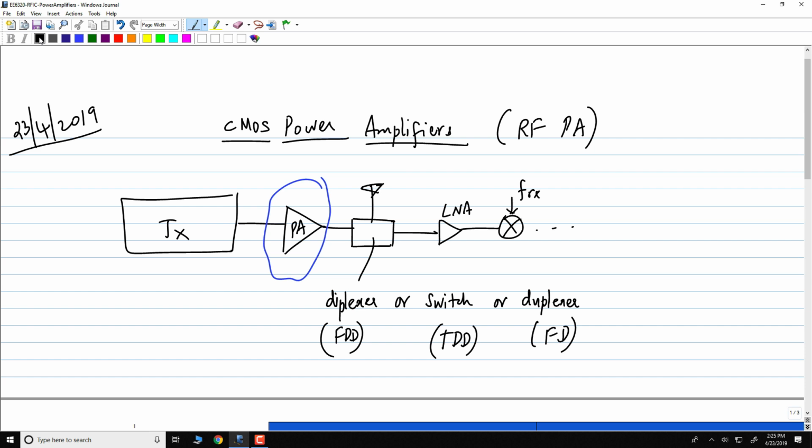We have that SNR floor and other minimum power. The first thing is the antenna itself has a noise floor of minus 174 dBm per hertz, right? Above that you add the SNR required. Above that you add 10 log of the bandwidth of the signal, correct? And finally you add the noise figure that the receiver is going to add. Remember, that's your link budget. That is how you get the sensitivity, right?